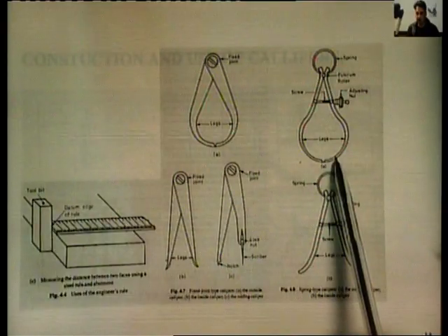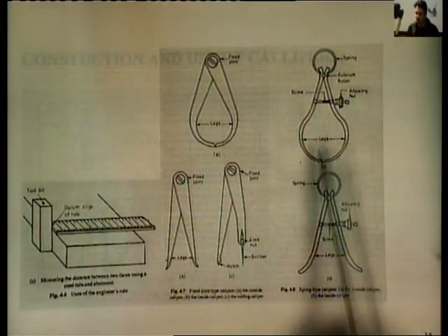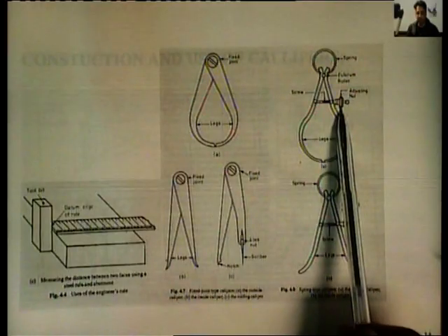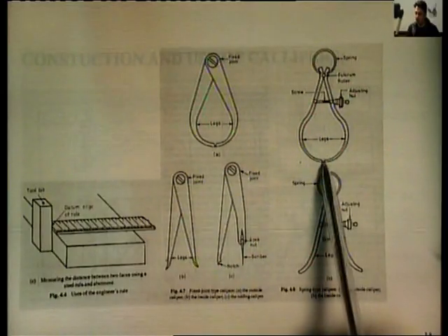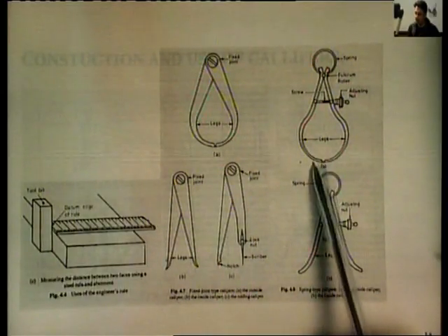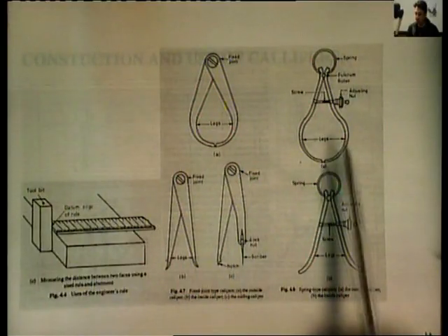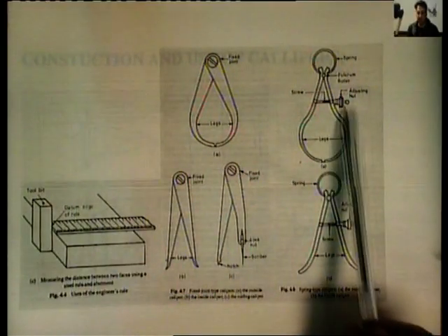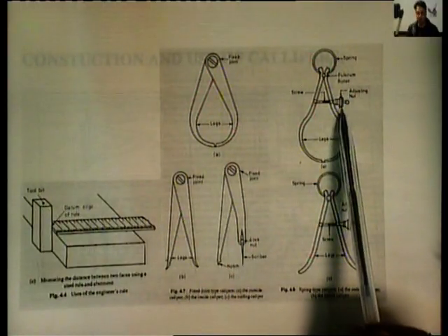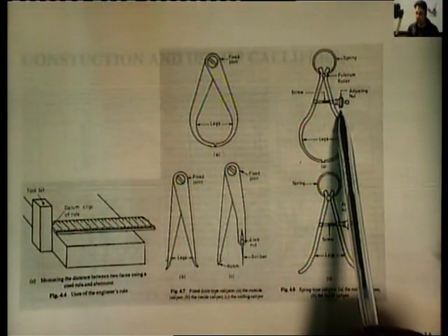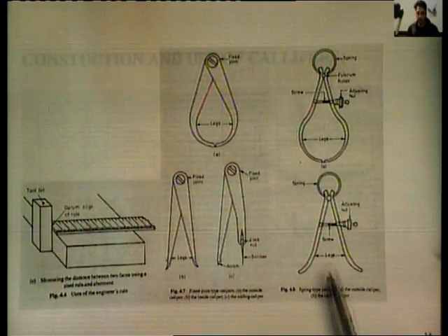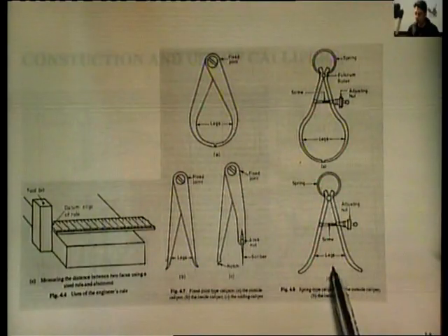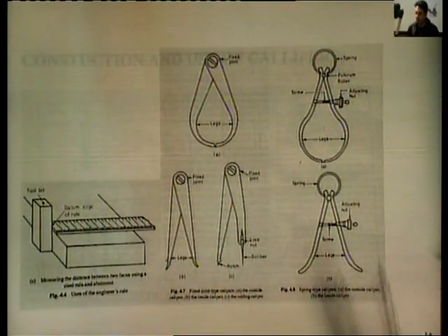And over here, this is the spring type of caliper, in which as we rotate this adjusting nut over here, this gap between the legs of the caliper is likely to increase. So, as we want to make a very fine adjustment, we will rotate this adjustment nut very slowly and with very little amount. Similarly, this one is for the internal dimensions, that is the inside caliper.